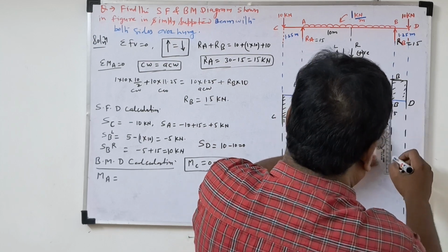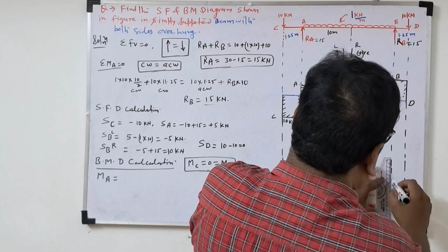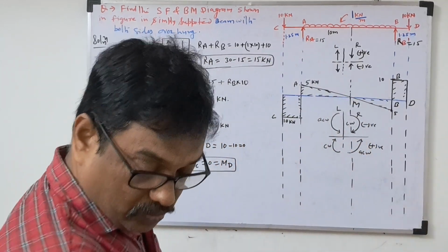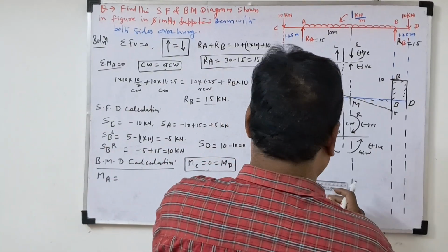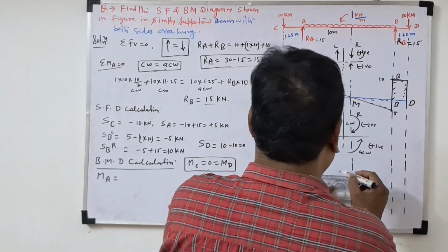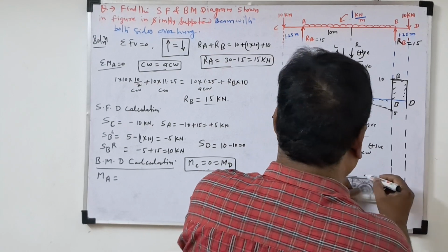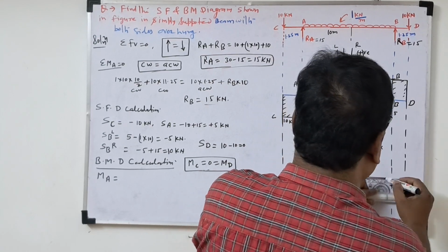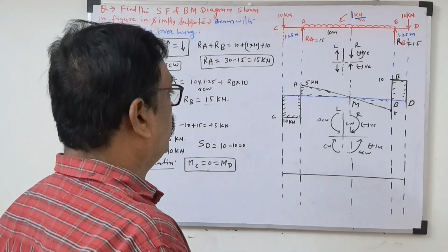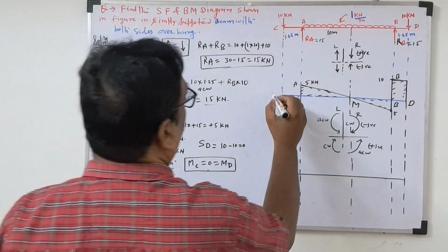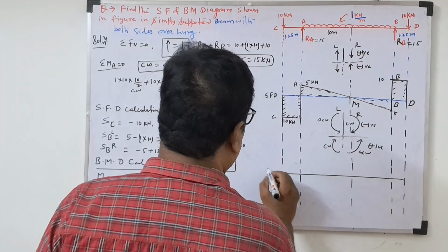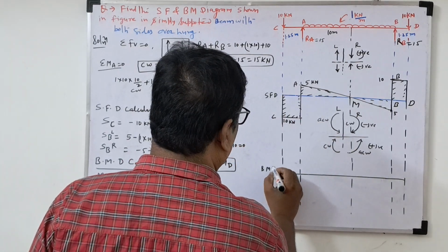Middle point also, this line, if you project a small line with a pencil or 2H pencil, it will be okay. So now we'll draw the zero bending moment line. In this line, bending moment will be 0. Like this here, shear force blue color, no? This line is the shear force diagram zero line. So you can write here shear force diagram line. This is the bending moment diagram line, you can write bending moment diagram.